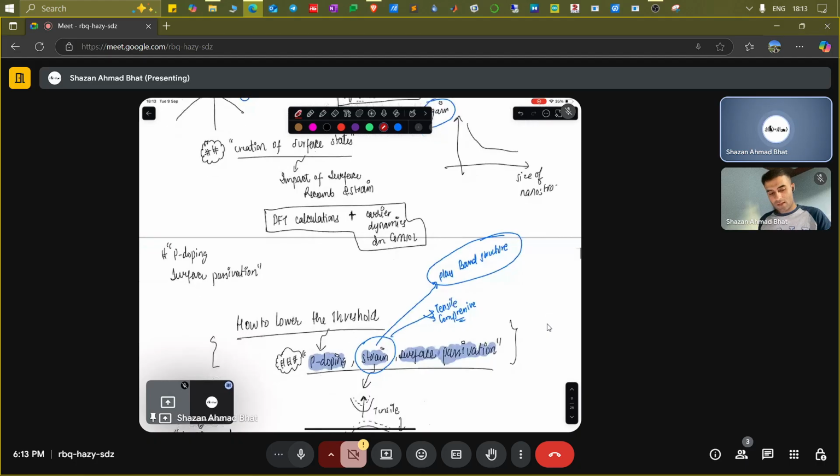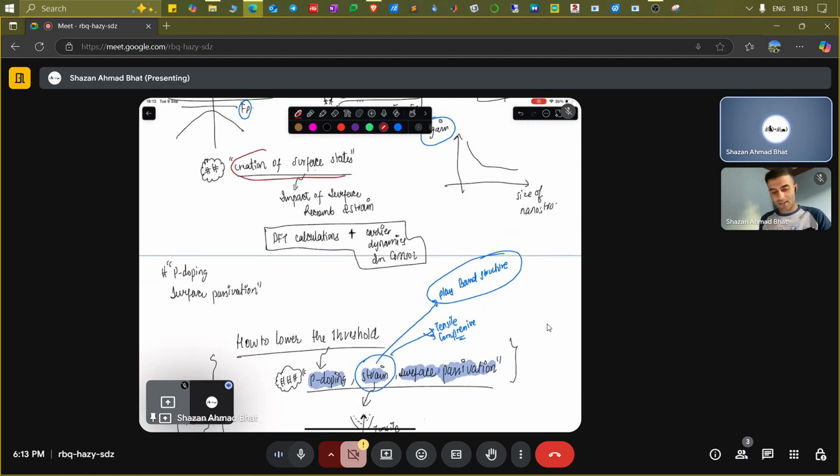Now there is something called surface states, which are certain states present at the surface. Even semiconductors have them. If this is a semiconductor where this is the Z direction, the growth direction, near the surface there are a lot of states available. These can be donor types or acceptor types, and sometimes because of this there is a bending near the surface, basically called surface bending. So surface states can be present here, even in the band gap. What it affects is something called surface recombination velocity.